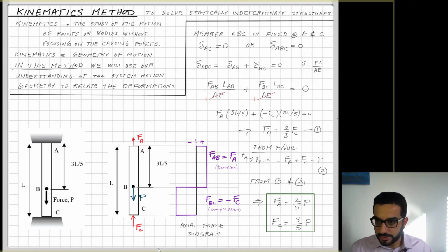So that will mark the end of this lesson. We learned how to calculate the axial deformation of a member, and we also used this information to solve for statically indeterminate members using the two methods, the redundant force method and the kinematics method.